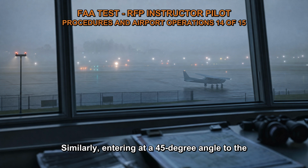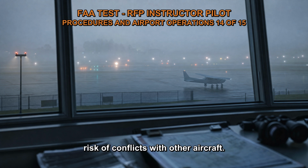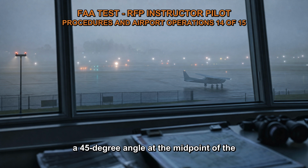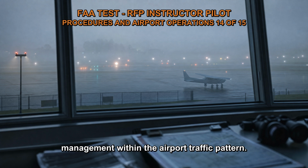Similarly, entering at a 45-degree angle to the base leg just below traffic pattern altitude can disrupt the flow of traffic and increase the risk of conflicts with other aircraft. Therefore, the correct answer is to enter at a 45-degree angle at the midpoint of the downwind leg at traffic pattern altitude. This entry procedure promotes safety and efficient traffic management within the airport traffic pattern.